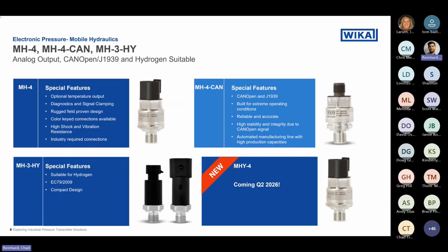If you think about signal clamping as an example, if you have a 4 to 20 milliamp output, you can actually clip or clamp that signal at 20 milliamps. That way, if you're lifting a heavy load and the signal's naturally going to go above 20 milliamps and cause your machine to act erratically, you can clamp at 20 milliamps so you maintain smooth operation. Pretty cool feature.